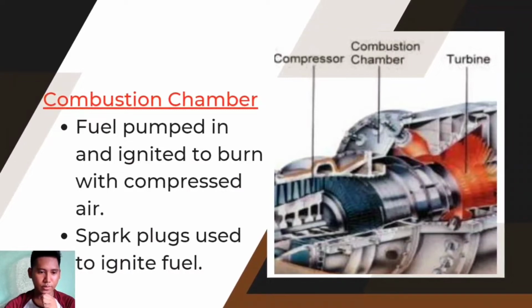The second part of the gas turbine power plant is the combustion chamber. In the combustion chamber, heat is added to the air by burning oil. The oil is injected through the burner into the chamber at high pressure to ensure atomization of oil and thorough mixing with air. The result is that the chamber attains a very high temperature, about 3000 Fahrenheit. The combustion gases are suitably cooled to 1300 to 1500 Fahrenheit and then delivered to the gas turbine.